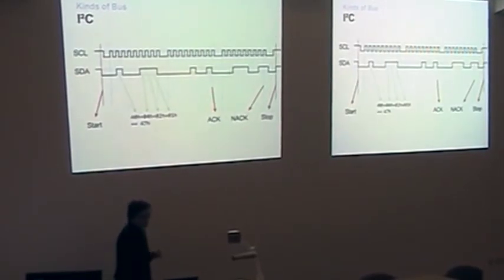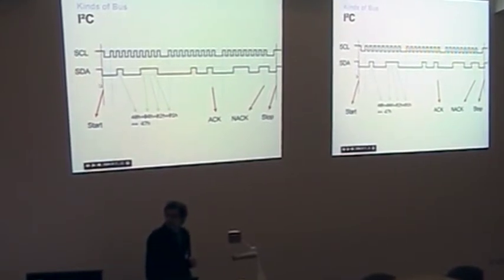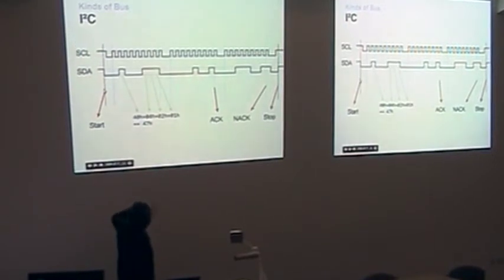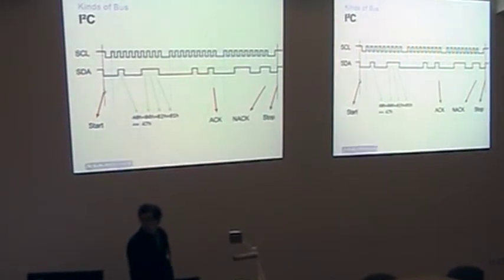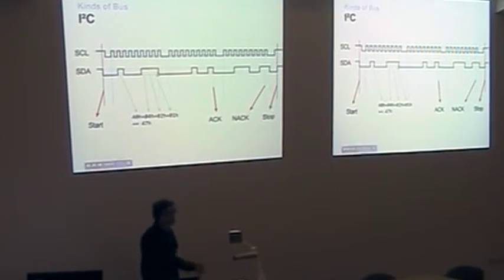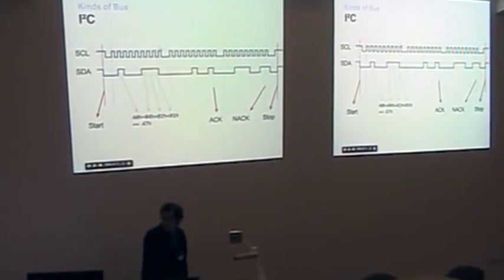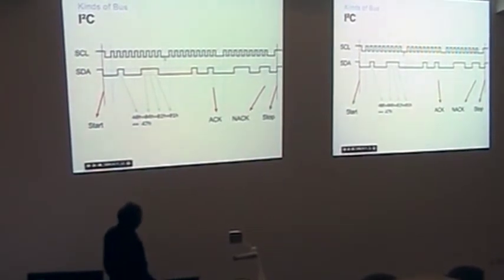So this is what I2C looks like on the wire. Slightly simpler. I should probably put some colours in to show that it's a bit more subtle than this. Once again, it's synchronous. You have the clock line here sent from the master. And it has this fancy little handshaking signal where it wiggles the lines in the right way to say, I'm going to start now. So you have this proper signal to say, start. So everyone knows what's happening. And then the master writes out this first byte. And the first byte is always the address of the thing you're talking to.